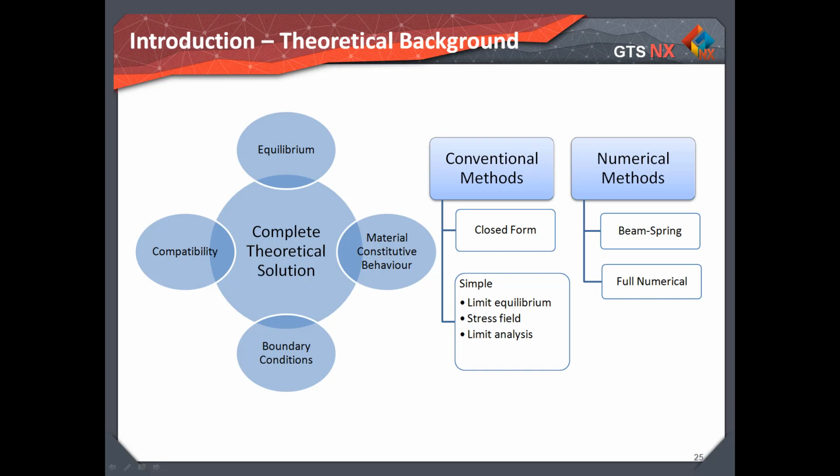In terms of the method of analysis, fundamentally there are two groups, conventional method and numerical method, which I will briefly describe. Closed form provides an exact theoretical solution, but it is based on the unrealistic assumption that soil is an isotropic linear elastic material.